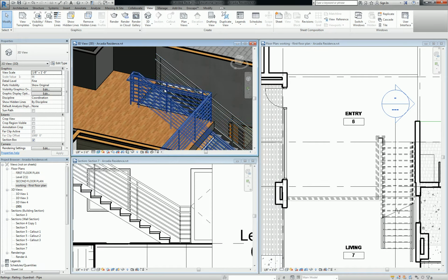I mean, it looks like it did. There should not be a difference. The idea, so like let's say we set our handrail at 36 inches off the floor, right? The 36 inches applies to the nosing of the stair as well. So if you look at it here, actually let's just do it this way. From the nose of the stair to the top of the handrail should be 36 inches, which is what that is. See, 3 feet.